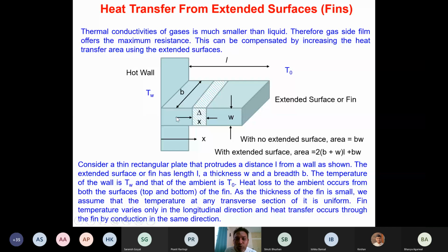So that is the reason why we are calculating it here, because only here the transfer takes place by conduction. If I look at any other location, there are two factors: there is conduction as well as convection, isn't it? So the amount of heat transferred along the longitudinal direction plus the amount of heat dissipated till this point, both these factors have to be accounted for if you look at the Q at any location. But that Q is also going to be the same as the Q here. Exactly at this boundary, I only have to account for the conduction, no convection at all. So that becomes easy, and that is logical also, isn't it?